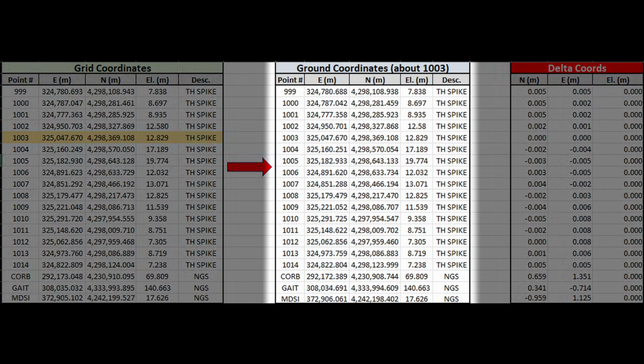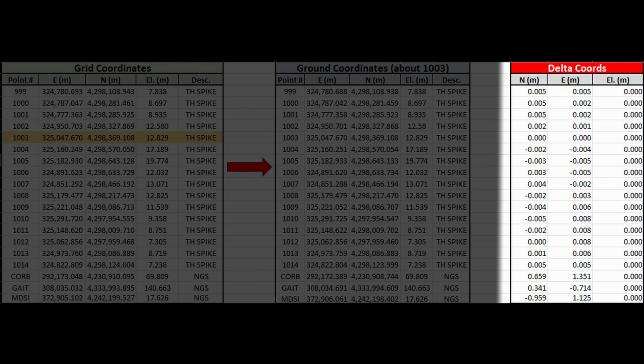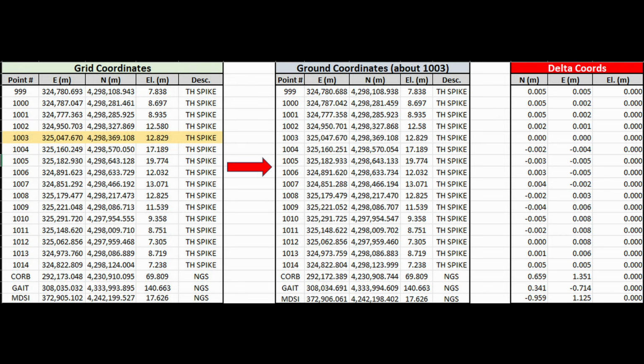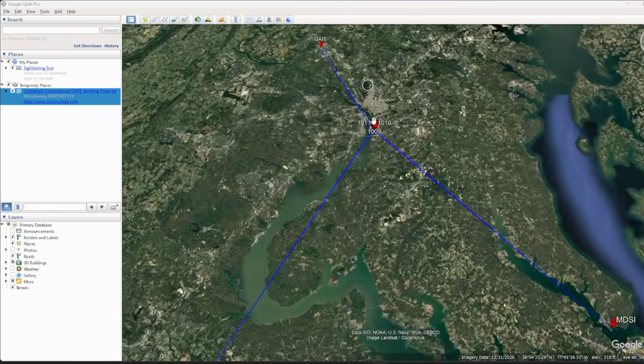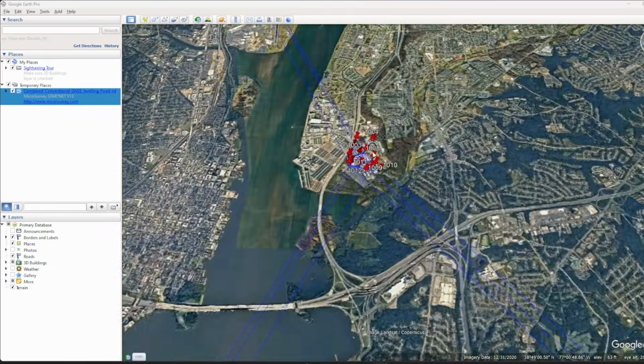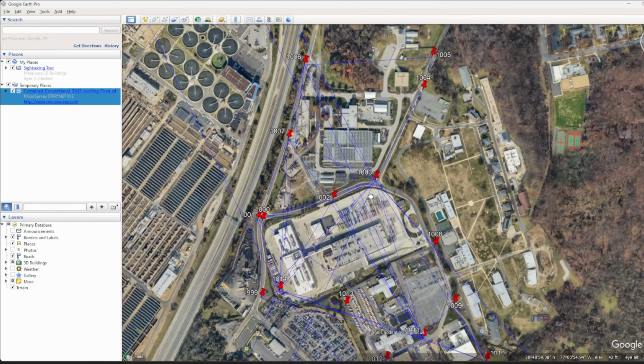What I mean is that right now, if we scaled about our scaling point, we have created another coordinate file, a scaled ground coordinate file, that is slightly different than the original grid coordinate file. It wouldn't be difficult for someone to mistake one of these coordinate files from the other. The advantage of not truncating values is that the ground-based coordinates will fall approximately in the right absolute location, so they will still line up decently with other data sources such as aerial imagery. The con is that it's easy to mix the two coordinate systems up.